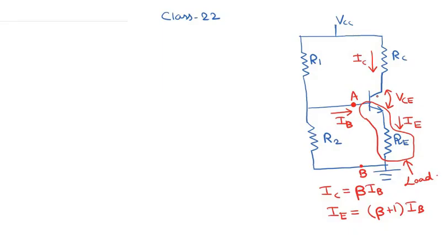We already know that an increase in collector voltage does not increase the base current or the collector current or the emitter current if the transistor is operating in the forward active mode. So an increase in the collector voltage does not change the base current. This basically means that it appears as if the collector and the base are basically electrically isolated.